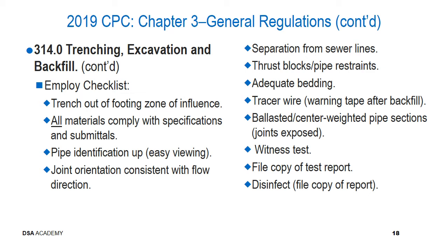You want to make sure that whatever the geotechnical engineer has identified should be happening in that trench is definitely happening. And you may also want to request that the laboratory of record or the geotech complete their soils curve early in time for you to review that before the trench starts having bedding placed in it.